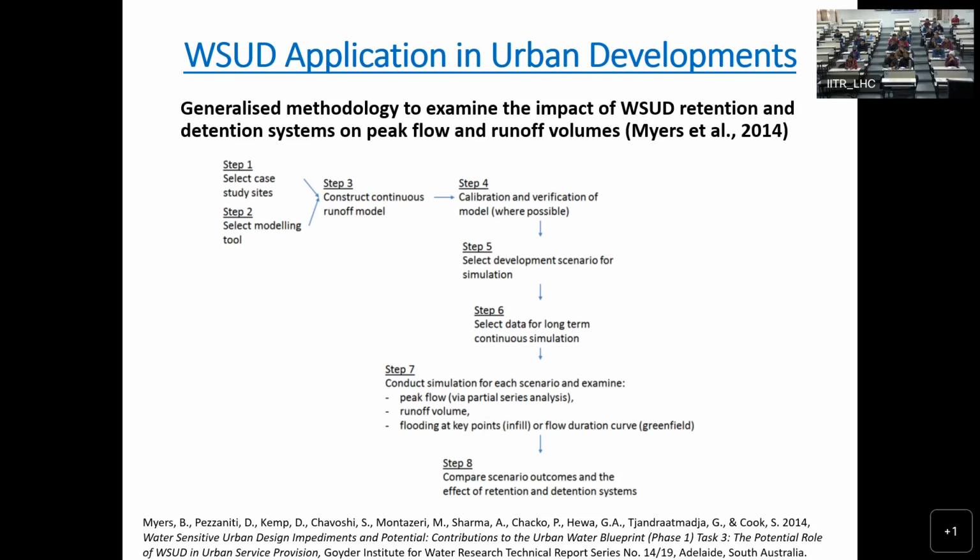So calibration validation is one of the most important aspects. And select scenarios means what options you are going to model. And that is based on a particular project, based on the conditions which you have to look into. There can be the climatic conditions, or maybe putting different types of infrastructure to see what impact it is going to have on the overall hydrology and hydraulics of that infrastructure or the catchment.